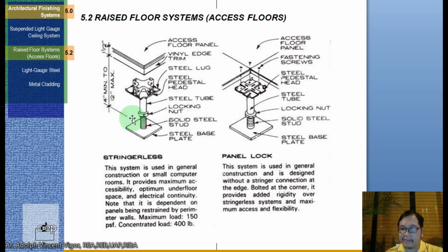So basically, the purpose of your raised floor, class, is to let the wires for the computers or for the electrical systems go under your floors. Okay. Just remember, class, that when you want to use the raised floor systems, I think it will be much better if you already considered it in the design in the beginning. Okay, so you won't have a hard time when you construct your building or structure.